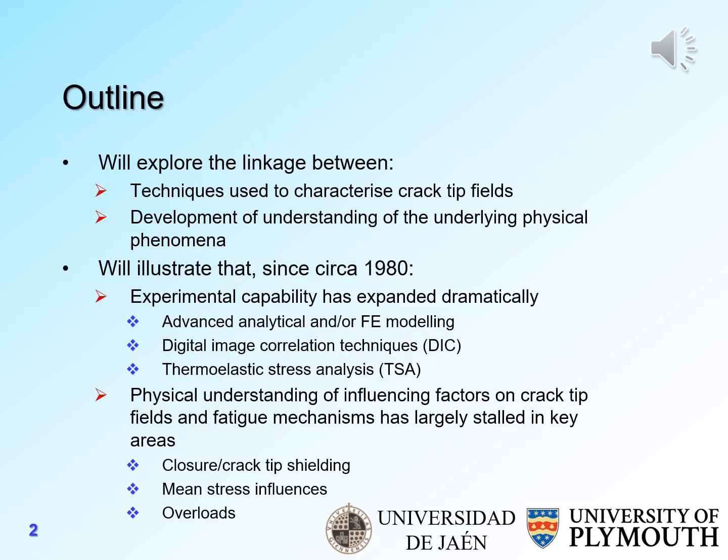I want to explore the linkage between the techniques that we've had over the past 30-40 years to characterize crack tip fields and how that's impacted on the development of our understanding of the underlying physical phenomena. And what I hope to illustrate, as I've already said, is that our experimental capabilities expanded very dramatically, but our physical understanding of the influential factors on crack tip fields and fatigue mechanisms has largely stalled in key areas, and these include the crack tip shielding I already mentioned, mean stress influences, and overloads.